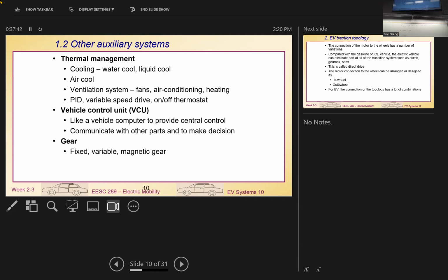So how to manage and process the signals is something we work on. We don't use that many cables; we use just a few cables with CAN bus, which is able to put all the signals into the same connection to feed to the VCU. All the companies have their own protocols for the CAN bus, which handles all this signal processing. So that's another area we can work on.